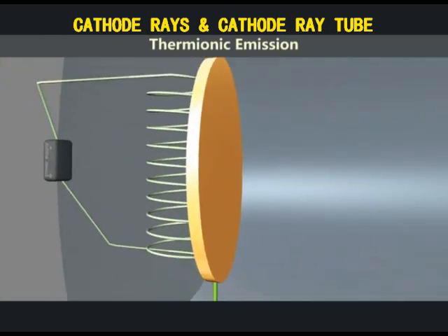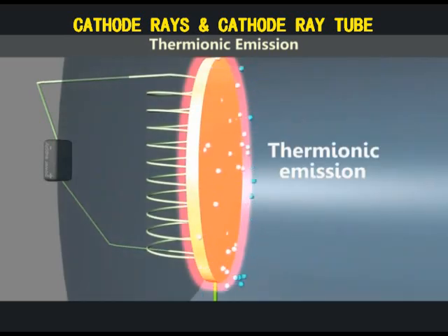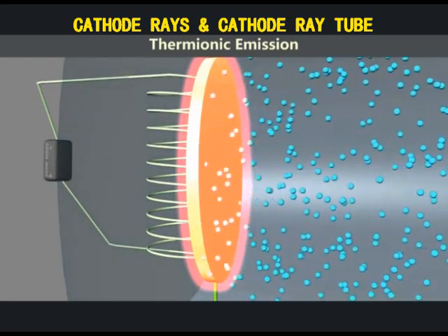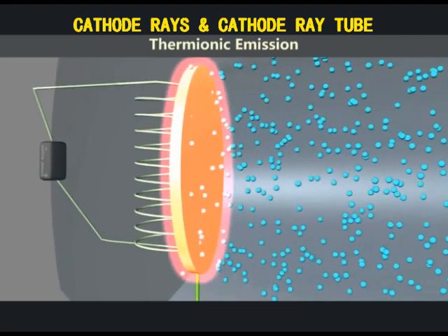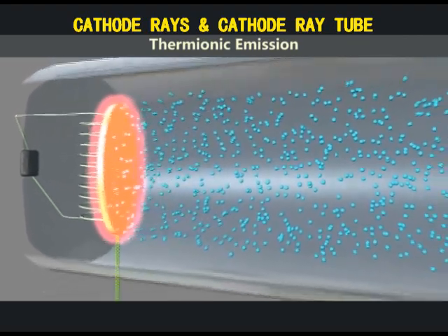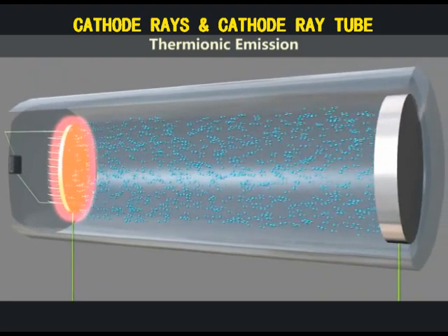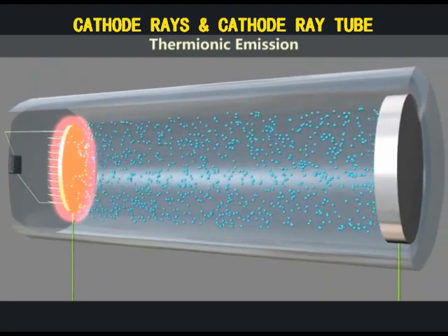When the cathode is heated, the electrons of the metal atoms are excited and move a little away from their nuclei and then back to their positions. But when the DC supply is switched on, the electrons are repelled from the negative cathode and attracted to the positive anode, traveling in the vacuum. So we get a beam of electrons traveling in a vacuum, reaching the anode and thus completing the circuit.